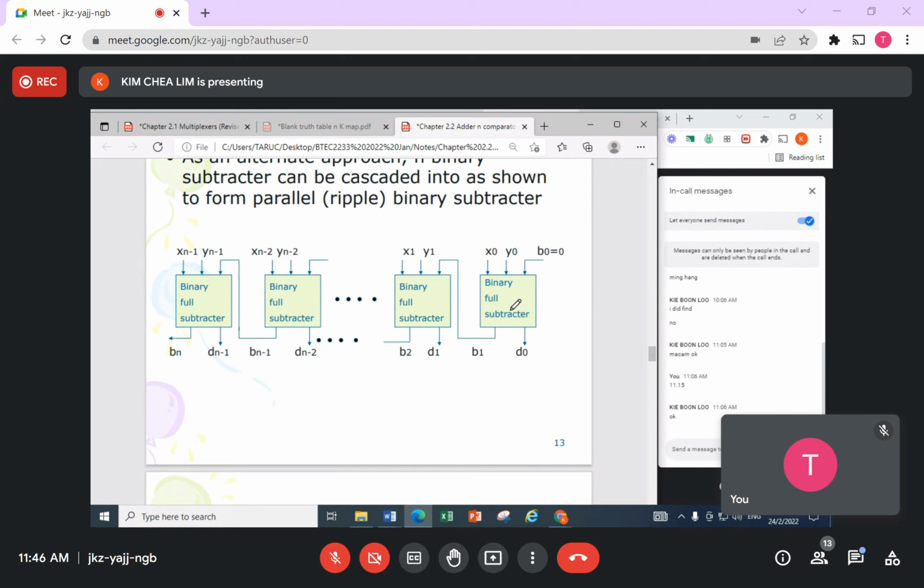All right, so again, you can have all your input x and y you put in at the same time. So parallel in, all go in at the same time. But the outputs here can only be accurate after a certain delay, depending on how much time every one of these requires to respond. Like the example just now, if I take 10 nanoseconds each, for the case of 4 bits, 1, 2, 3, 4, I only will see my correct result after 40 nanoseconds.